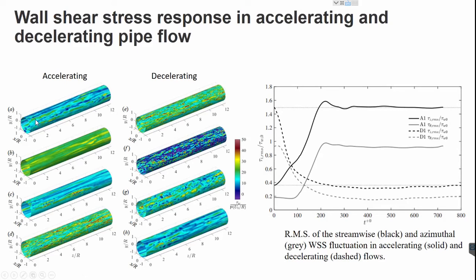And this has this streaky behavior, and we have these typical streaks, which is the organization we have turbulence near the wall. But as we start accelerating, these meandering streaks start elongating. Okay, so they elongate and they become more stable. And at the end of the pre-transition, we will see these turbulent spots here. And these turbulent spots will later propagate throughout all the pipe, throughout the domain.